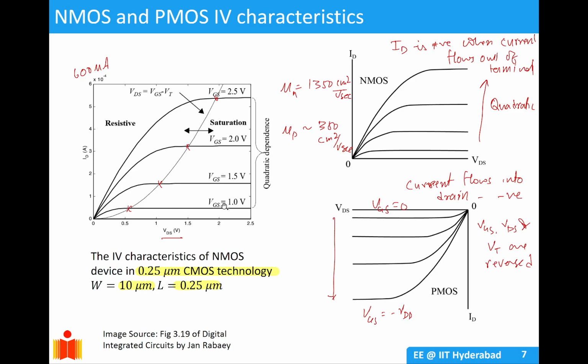So you can see here for VG1, your saturation current is very small, and as you increase your VG, you can see your saturation current increases as a square law, and you can fit your pinch off regions on a square curve. The pinch off region is VD equals VGS minus VT. So when you plot that here, you will see it falls on a square line.